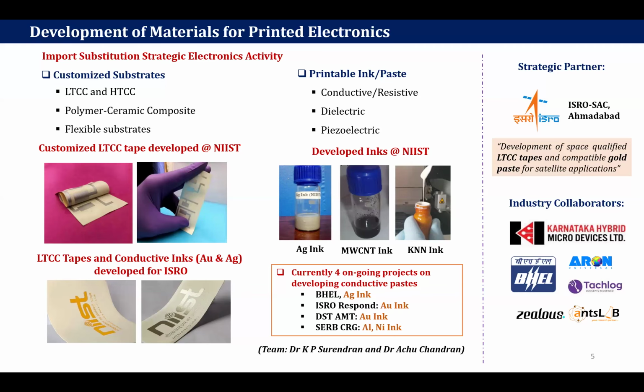In the green stage, the LTCC tapes are flexible. These are machinable ceramic tapes, so you can drill holes, make cuts, wires, and different kinds of structures over them. The stacking of these will give a complete module. Different functionalities can be incorporated into different layers, and subsequently the complete system will address a particular application.